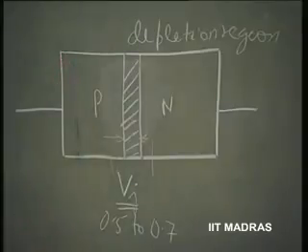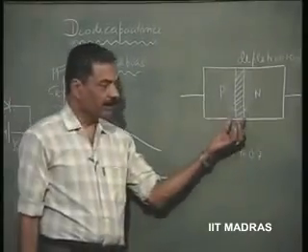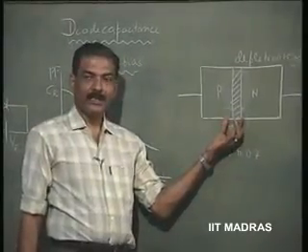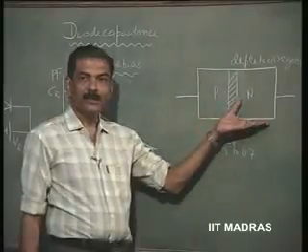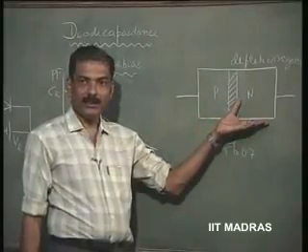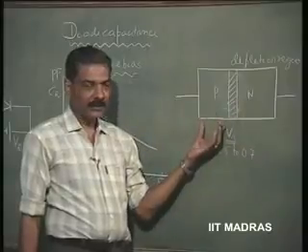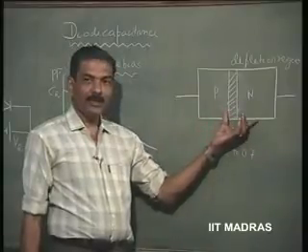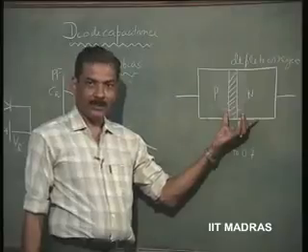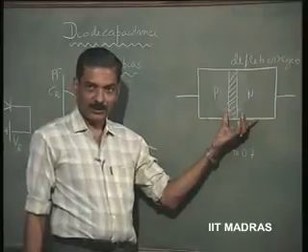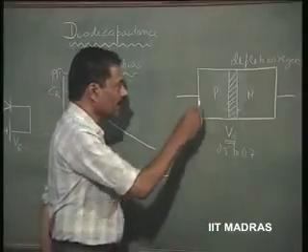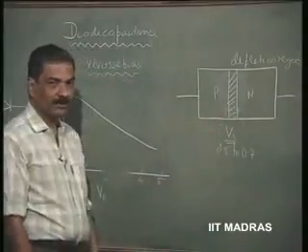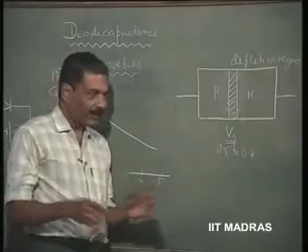So, it is equivalent to a capacitance. When it is reverse biased particularly, we know that current is not flowing at all. That means the reverse resistance is very nearly infinity, but it can now be equated to a capacitance, not just an open circuit, but a capacitance really.